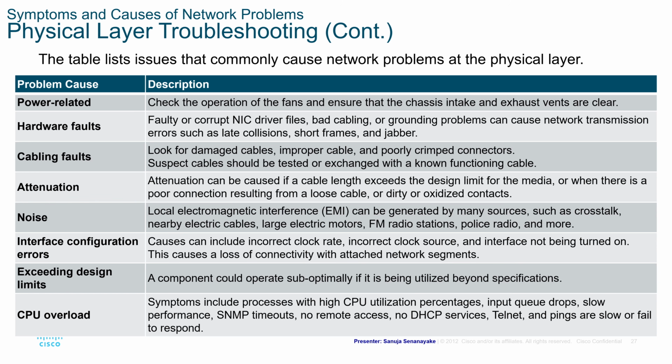If the cable length is too long, the system might work one day and not the next, might work in the morning but not in the evening, and so on. That's an example of exceeding cable length, creating signal attenuation as a result. The cable is not designed to run that long, hence when it exceeds the design length for operations, it's going to result in significant signal attenuation.